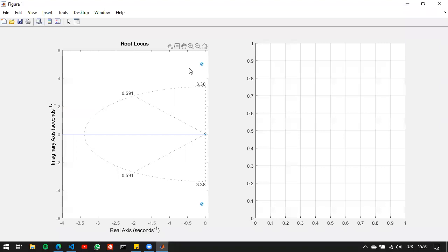So the poles and zeros in the dominant region were close to each other. Instead of placing them with a certain distance, what I did is I got rid of them. I just canceled them out. Now the only thing left to do here is to choose the p-type controller gain that results in the pole at 2 here.